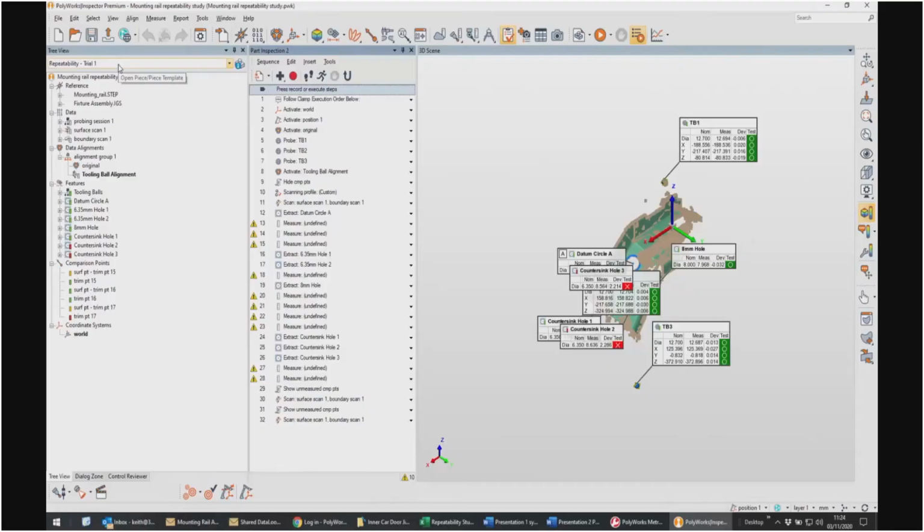So I've got word from the quality team that all 10 measurements are completed and have been uploaded to DataLoop. So I've logged in and downloaded the project. I can see that all 10 pieces are in the project. So now I'm ready for the repeatability study. I'm going to use the Excel spreadsheet provided by Polyworks to calculate variability.